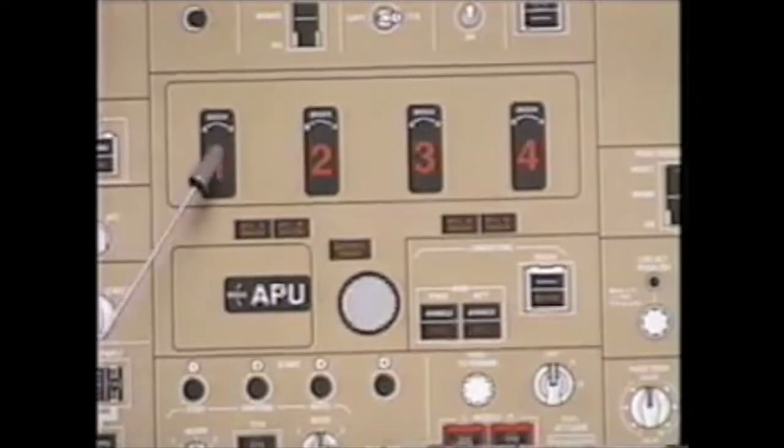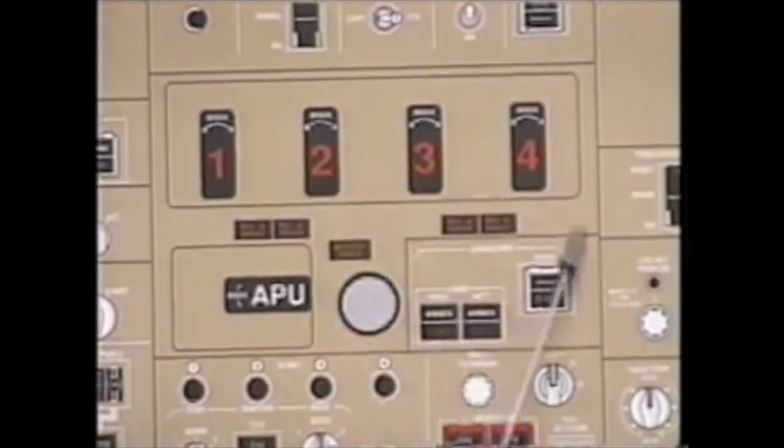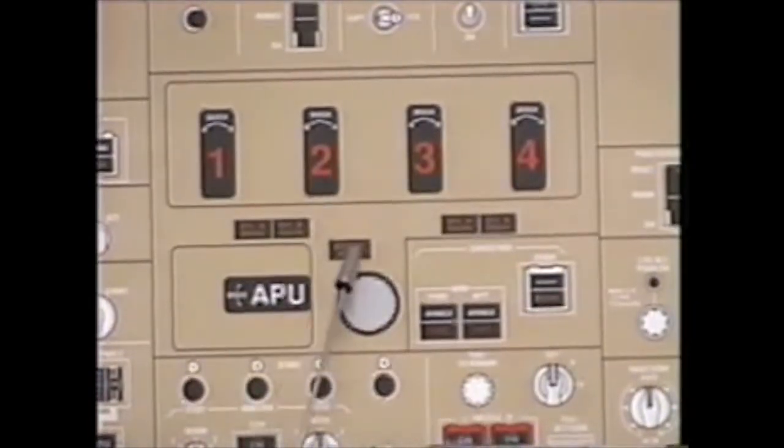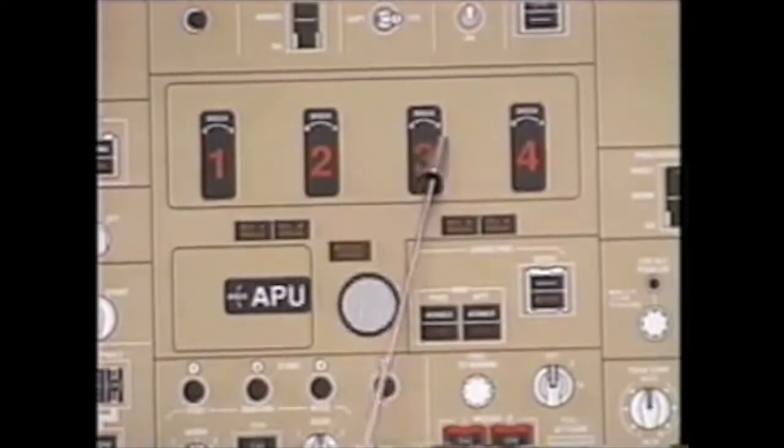Engines 1 and 2 on the left wing share 2 bottles, bottle A and bottle B. If you discharge bottle A into one of these engines, bottle B can also go into that same engine, or it could be discharged into the other engine. There is no way to get these 2 bottles on this wing over to the other wing. Likewise, there's no way to get the APU fire bottle to either wing.